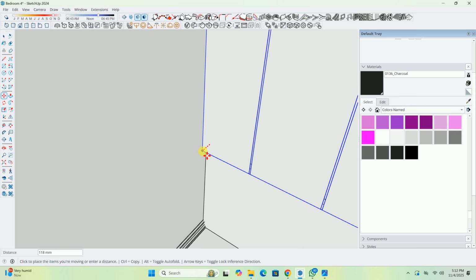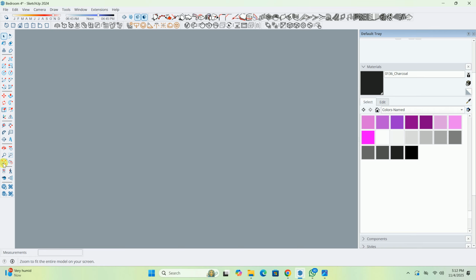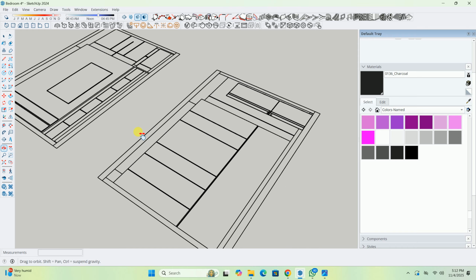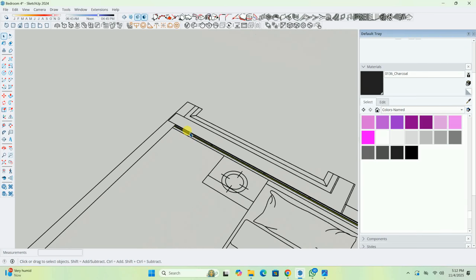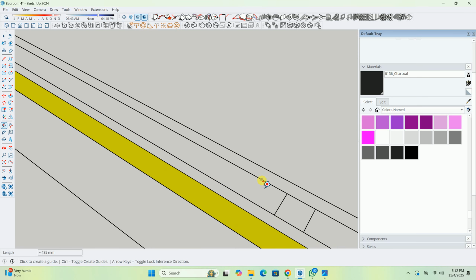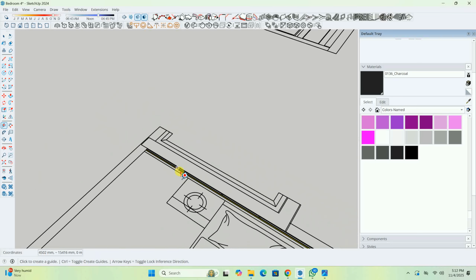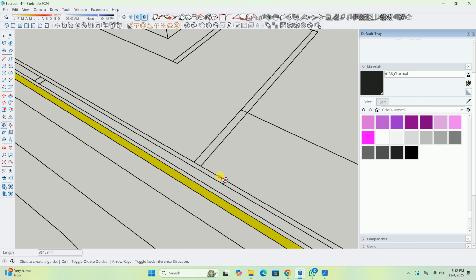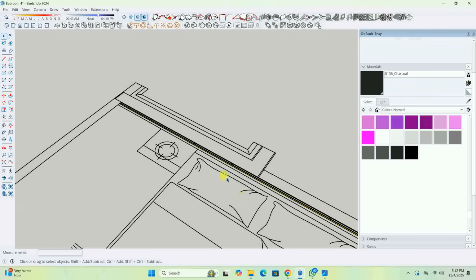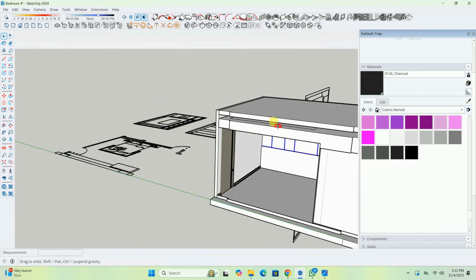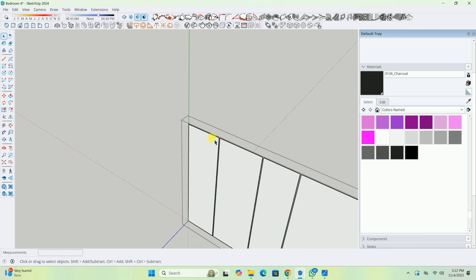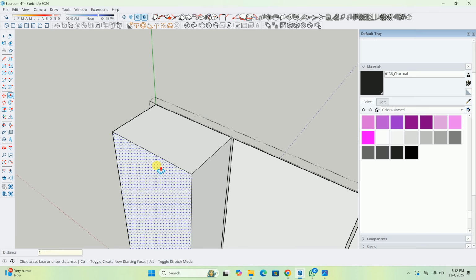what was the width that we have taken? It would be mentioned in this elevation. So first of all, 6 mm ply, then 12 mm board. Okay, so it's a 12 mm board. So I'll double click on it. I'll apply a push pull of 12 mm.